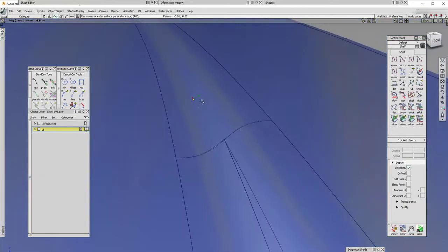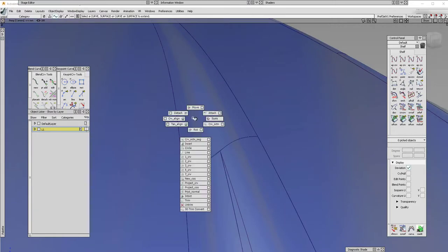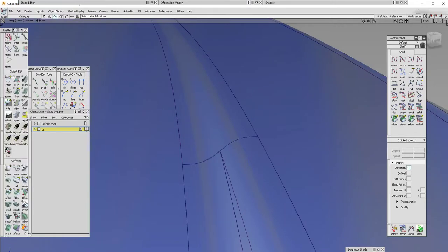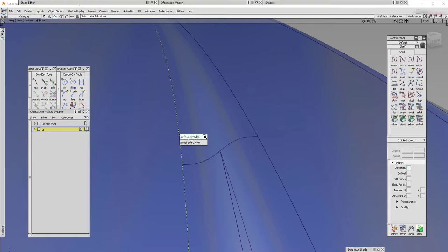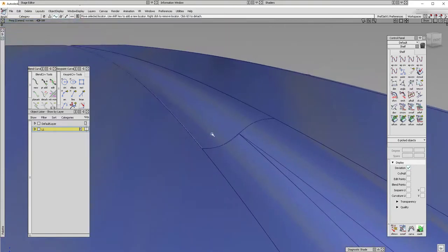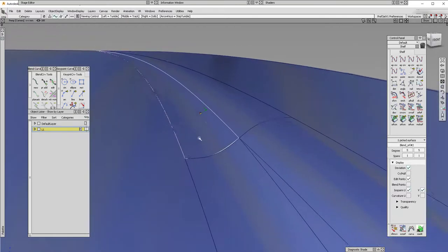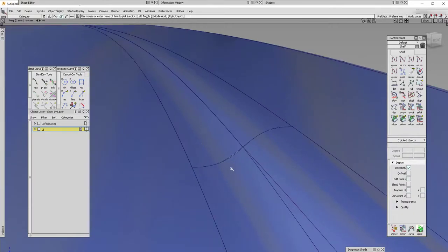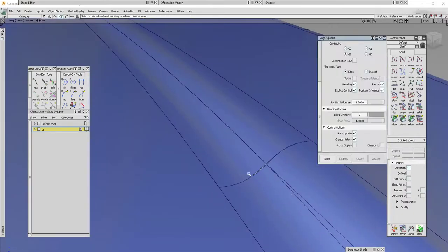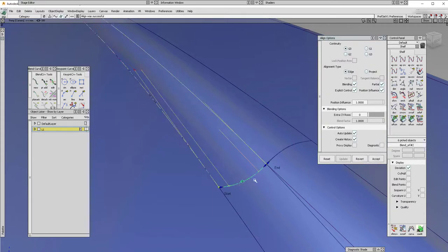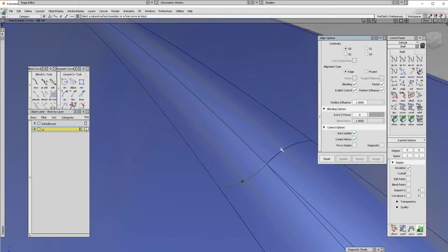How do we do that? We can try to detach, under the object edit menu, the detach tool, to detach this blend surface by pressing and holding Alt and left click right in the middle, hit go. Okay, now it seems like we can do some aligning here. Let's say positional align in the first place, and this one to this one.